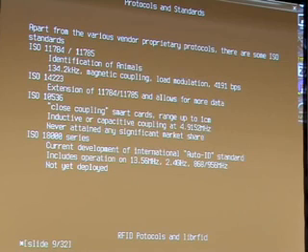And then there's a standard that almost nobody knows of. It's ISO 10536, which is close coupling up to 1 centimeter, which is not really very practical. I mean, if you need to be as close as 1 centimeter in order to make the device work, then you can use contact-based interfaces in most places anyway. No point in using an RF interface over the distance.